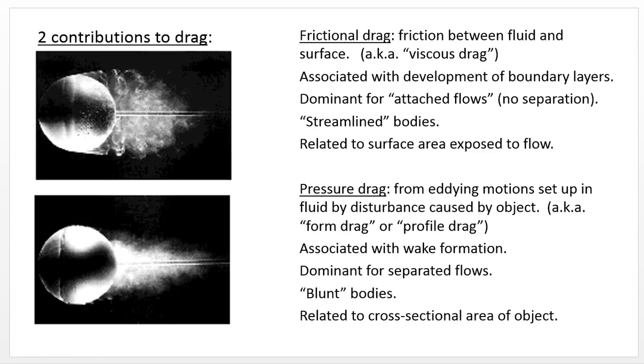So finally, we'll illustrate this with a real-life example. Here's flow past a ball. This is an image showing the disturbed flow in the boundary layer. This is a case where it's in the wake. This is a laminar boundary layer. We have a large wake. In this case, they use a tripwire upstream to transition the flow from laminar to turbulent. So we have a turbulent boundary layer.